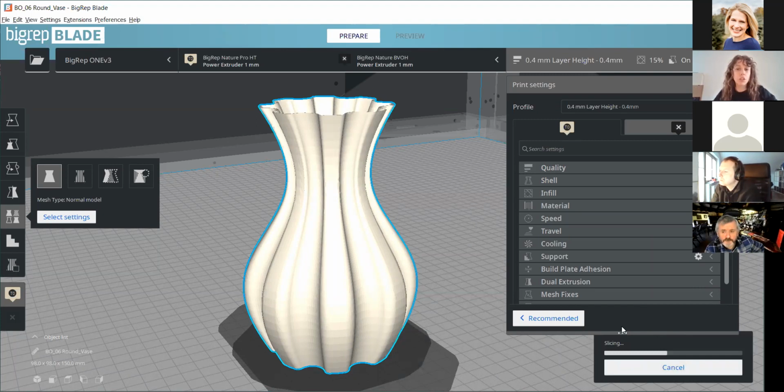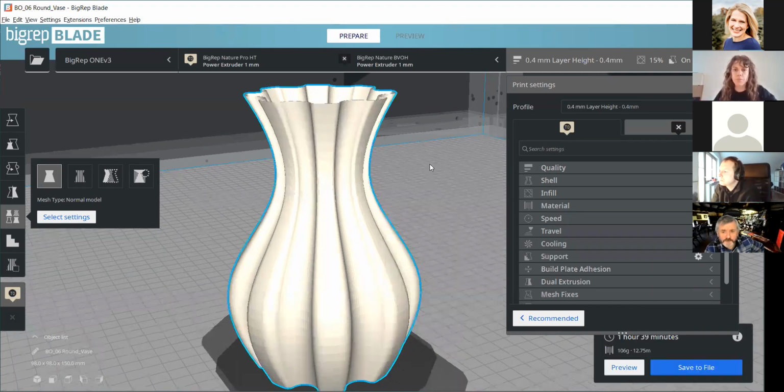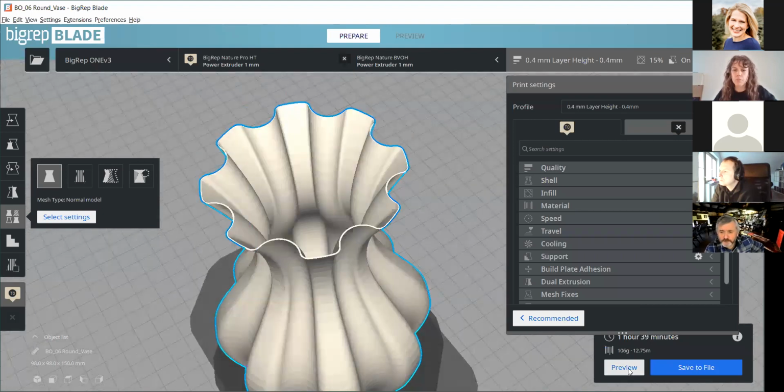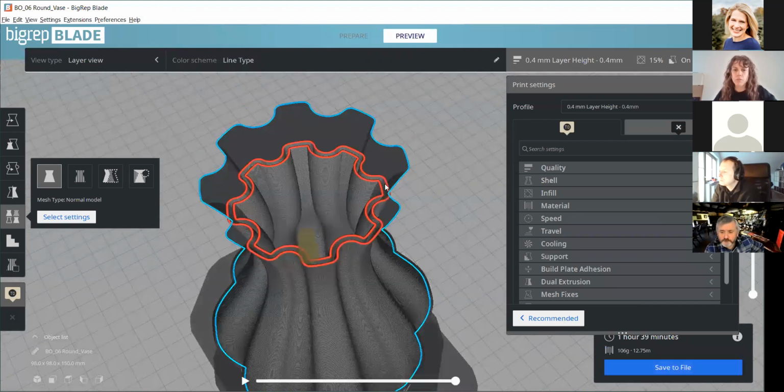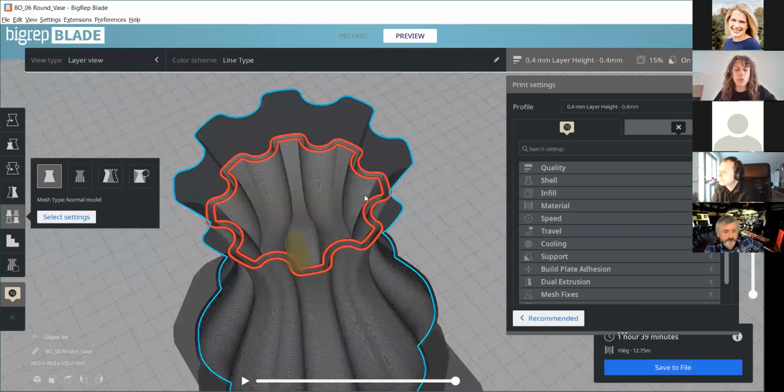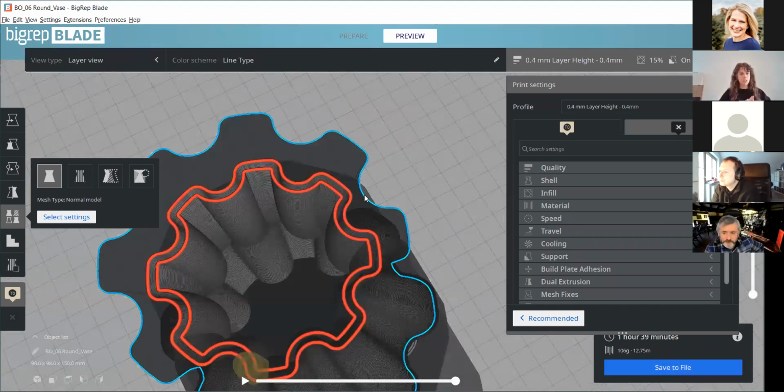It might still be too thin, and if it is, we can add more to the horizontal expansion. Okay, so now it's doing the 2 lines. As you can see, because I have it in surface mode only, I made it maybe a little too thick now, so having only 2 loops is leaving a huge gap in between. Not sure when this might be useful to you, but you understand how the process works.